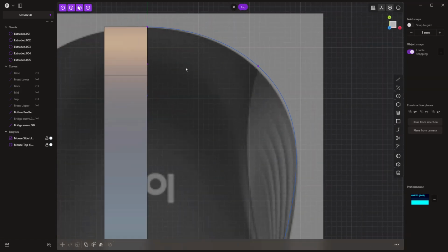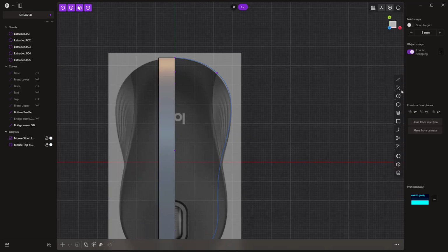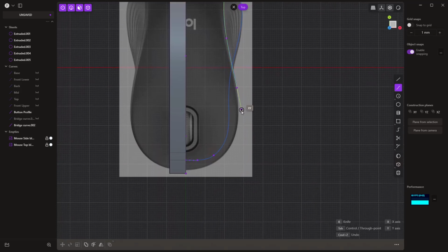But again, we're going to do this kind of incorrectly so we can see how to fix it. So I'm going to start with just my basic spline curve. I'm going to snap here, which, keep in mind, is potentially bad because it's in 3D, but I'm going to snap there, hold down control so there's no persistent constraint, and work my way forward.